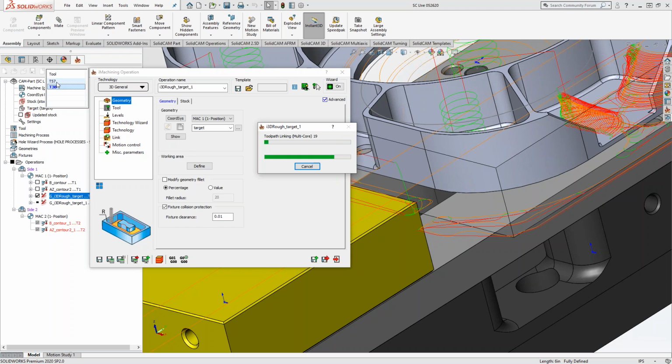It doesn't see any of the parameters I'm plugging in there, which is very useful for the multi-tool functionality, because you can imagine that let's say I switch to a completely different tool to do some of this, the semi-finishing, the semi-roughing, and it needs to have an extended length, and I don't want to have the same technology wizard settings, or I might be using some sort of bull end mill for certain applications throughout this selection of multi-tools. So the fact that you can get a separate set of parameters for each tool literally makes this 2 toolpaths in one window, because you get that individual functionality.